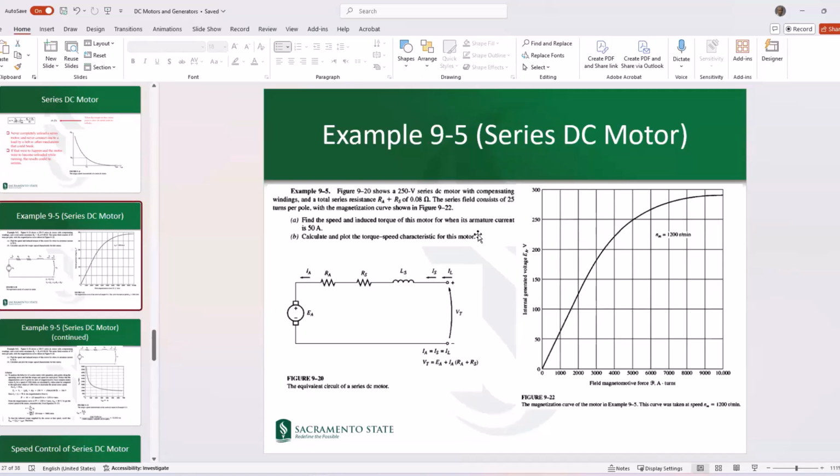So you don't want that. Therefore, because IF in the shunt motor circuit is smaller compared to IF in the series circuit, the number of turns in the shunt circuit should be higher compared to the number of turns in the excitation circuit of series DC motors.